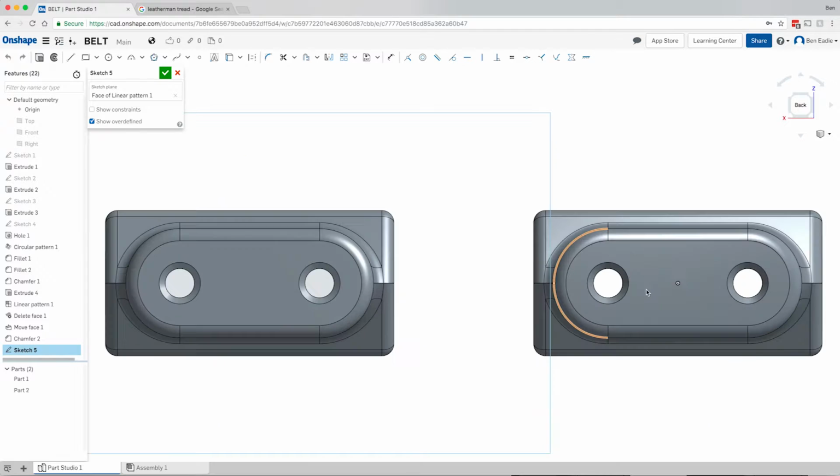Hit the F key because that'll bring everything into focus, and then we've got the two parts that we need to actually focus on. If we want to create a couple of holes and join these two pieces with links, let me think how I'm going to go about doing this. We're going to try some different things.